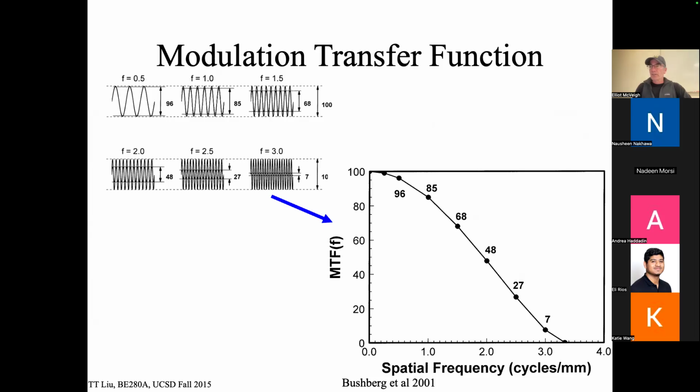So does it matter that I'm using deep learning to denoise this? What happens to my modulation transfer function after I apply deep learning to the picture to smooth the noise? Do I still get the same edge response or the same modulation transfer function? Probably not. It probably rolls off a little bit sooner such that it's a bit smoother, right? But if it's an amazing deep learning denoiser, maybe it sticks pretty close.